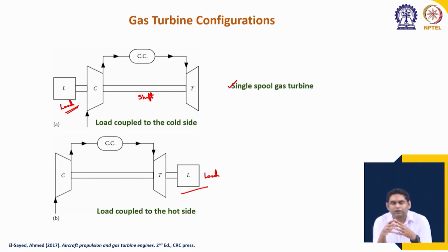As a result, in the lower stages of the turbine, towards the exhaust region, the density is very low and the specific volume is very large, which requires a very large passage area for the flow, which means that the turbine blades, as we will see later, have to be very long.